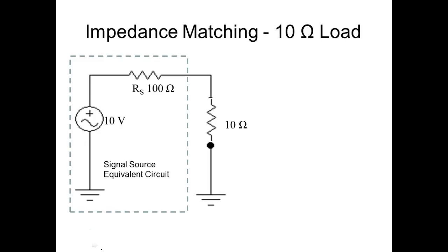The amount of voltage this resistor drops is relative to these two resistors. So the voltage divider formula says I can calculate any voltage. It's called VRX, whatever resistor I want to drop it across. This only works in series circuits, because that's when we get voltage dividers. And this is going to be RX over RT times VS.